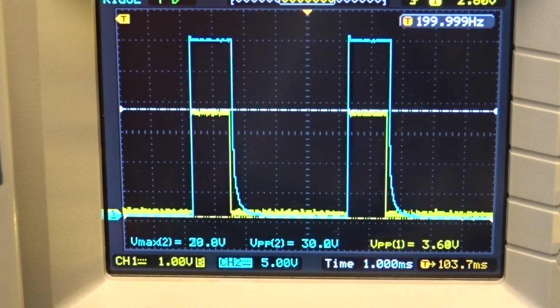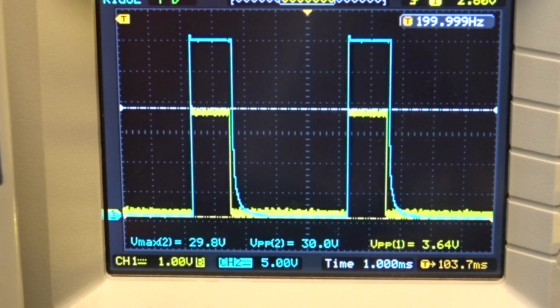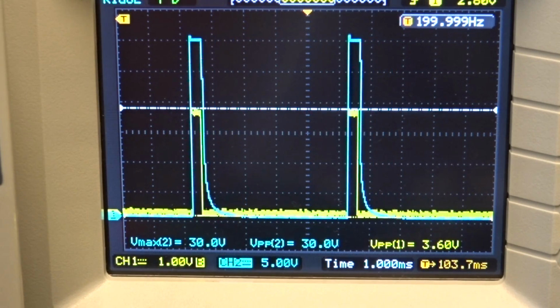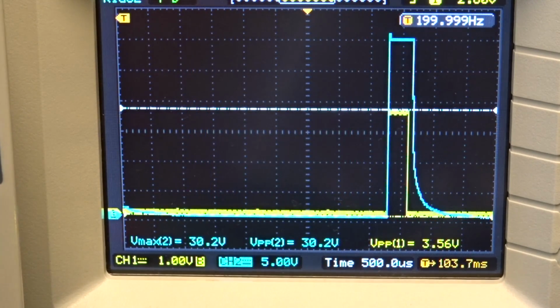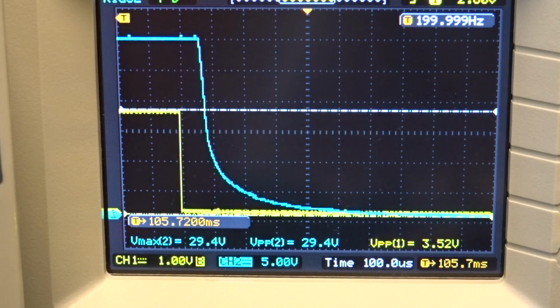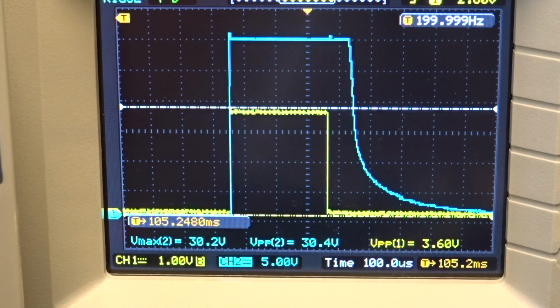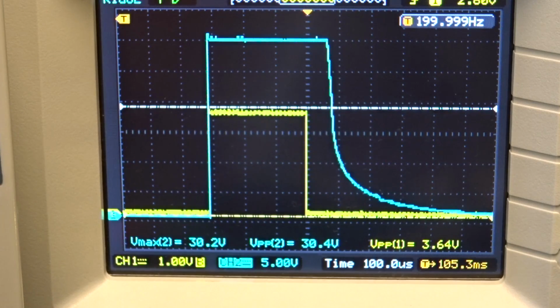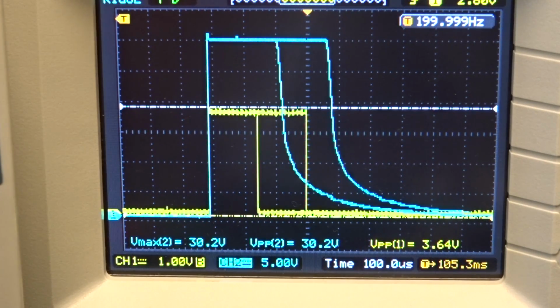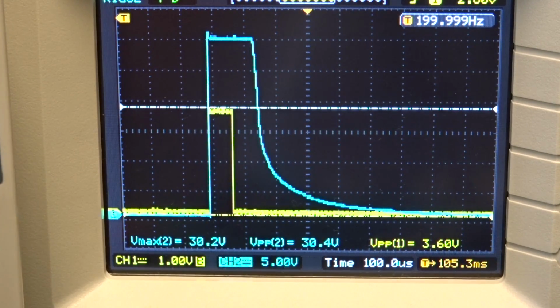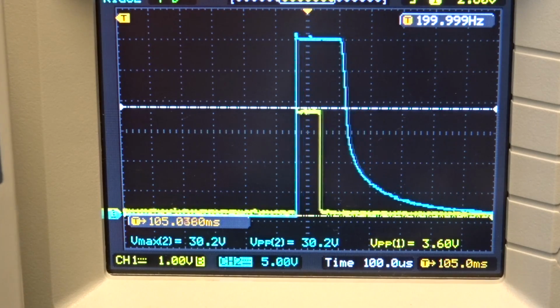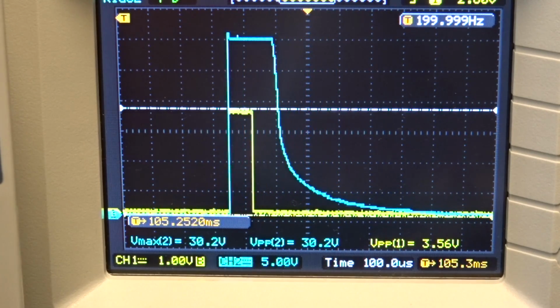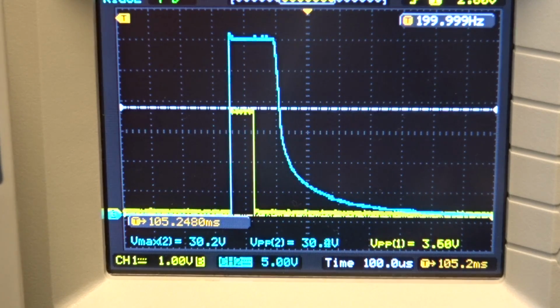So now let's lower the duty cycle of our GPIO pin and we can compare the different lines of our P-channel switching. And below a certain level we see that the switching off of our P-channel MOSFET doesn't really follow our GPIO pin, and it even gets worse if we lower the duty cycle again.